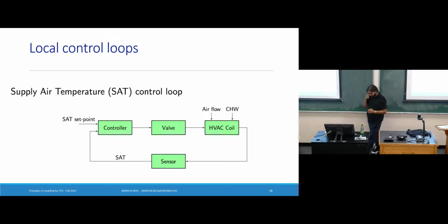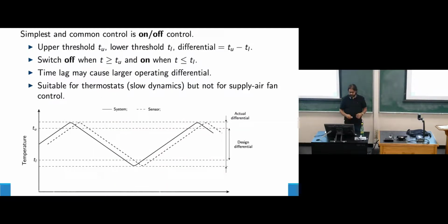Okay, good. So in reality, I just want to say this because I always want to keep one foot in the real world and one on the slides. In reality, most PIDs may not be that well tuned. So if that sentence didn't make sense, don't worry. In the real world, many systems work in this manner, where the user specifies some desired temperature, which is not actually shown in this picture, but we create a band or a region around that desired temperature, and we let the system just ride the upper and lower limits of this region.